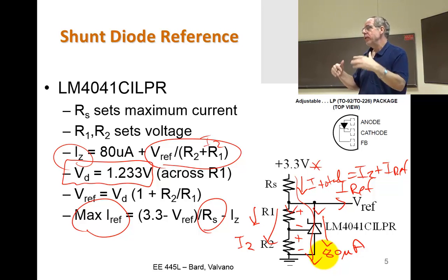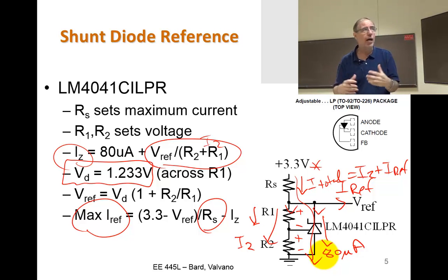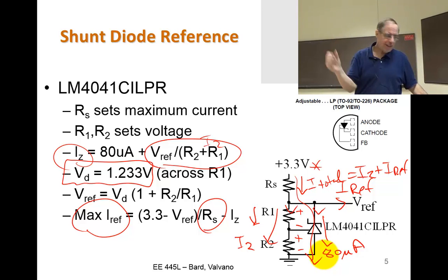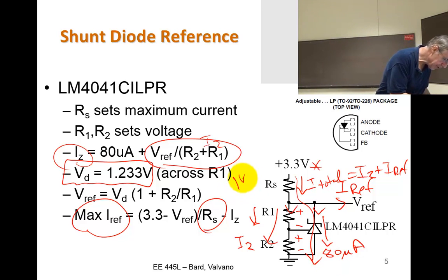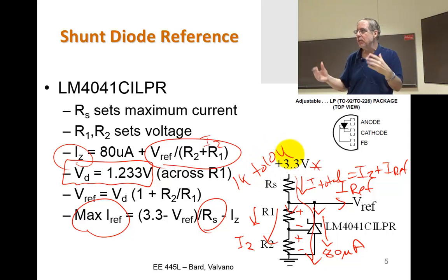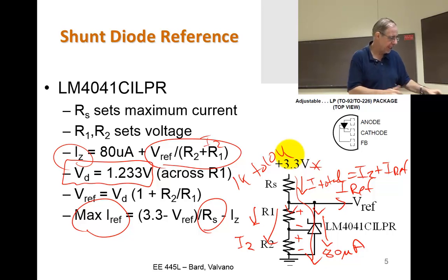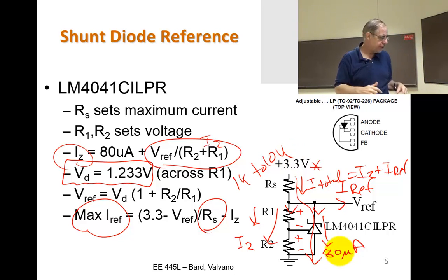And this is important when you solder your thing down in lab 11 or use it in lab 9. My guess is this resistor ought to be somewhere between 1K to 10K. If it's much less than 1K, you might be doing something wrong. If it's much greater than 10K, I'm sure you're doing something wrong, because 10K is not even enough to drive the chip itself. Okay? So watch out for this resistor.